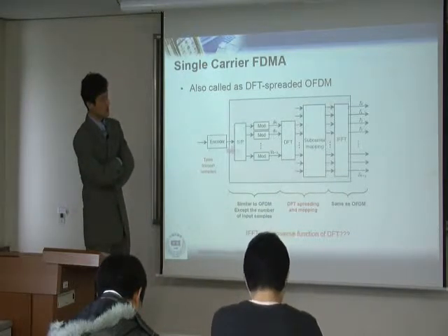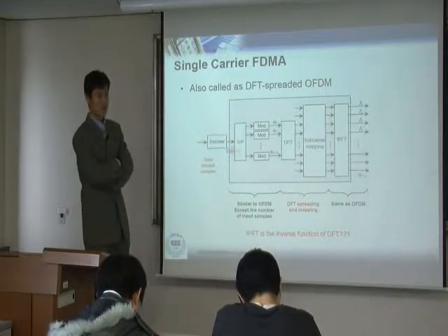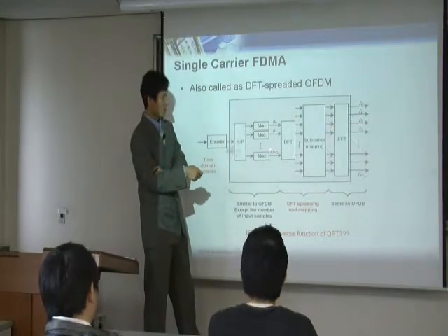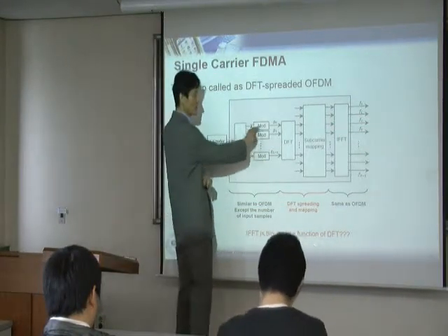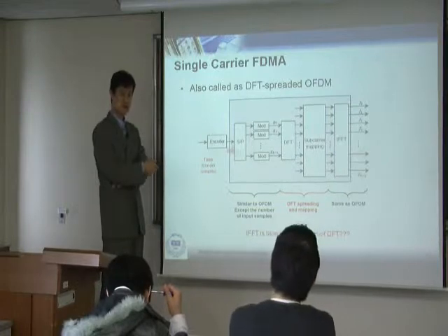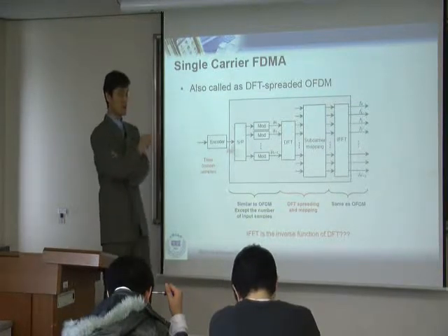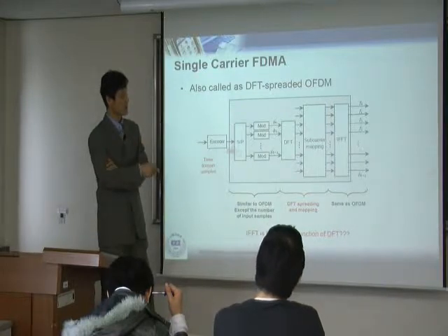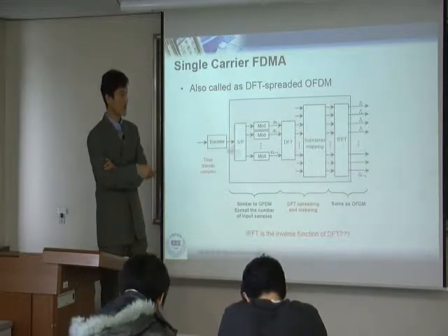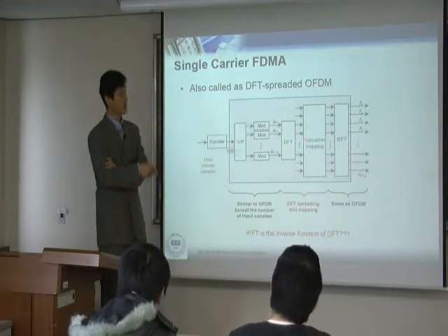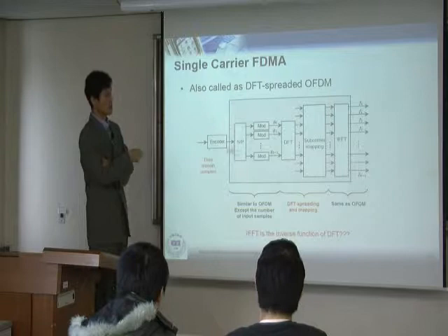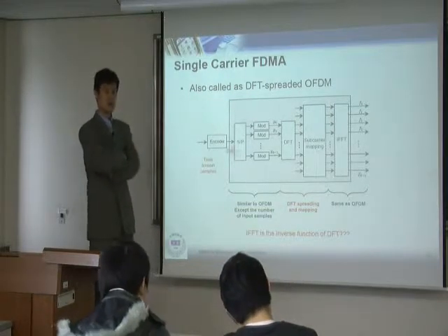This picture actually looks pretty similar to OFDM. This one still has IFFT. Still has a modulation for each of them independently. You still have a serial to parallel, same for the encoder. It looks pretty similar. What is different from OFDM is that in this case you have an additional block called the DFT. We have a DFT block. That's additional, and a little bit additional is the subcarrier mapping. We have these two. This is a new block, but fundamentally this looks almost the same as OFDM.